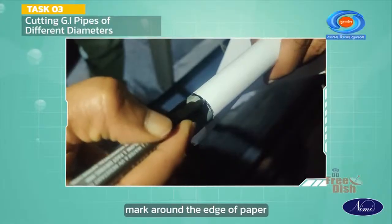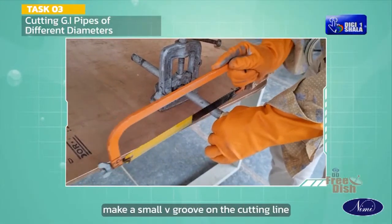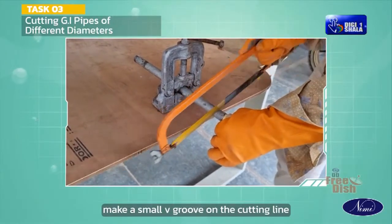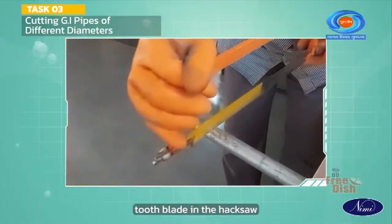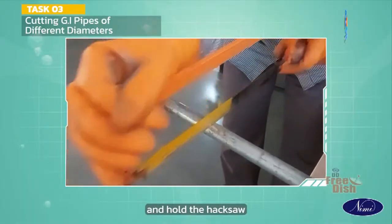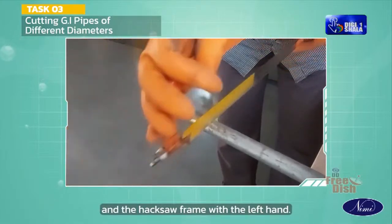Mark around the edge of paper using a pencil. Cutting the GI pipe. Make a small V groove on the cutting line with the help of a knife edge file. Fix the fine tooth blade in the hacksaw and hold the hacksaw handle with the right hand and the hacksaw frame with the left hand.